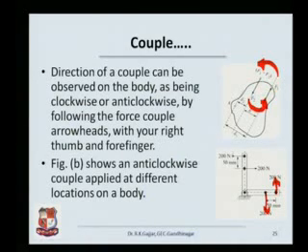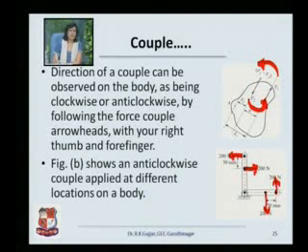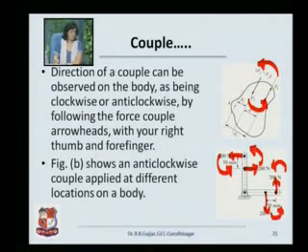Similarly, we have another force system, 200 newtons, equal and opposite but parallel to each other, therefore another force couple system is being formed over here. Both of them are going to have the same magnitude moment M equals 200 into 50 mm. Both of them are going to try to rotate this particular body in which direction? In the anti-clockwise direction. See, this couple is going to rotate in the anti-clockwise direction. Similarly, this couple is trying to rotate in the anti-clockwise direction.